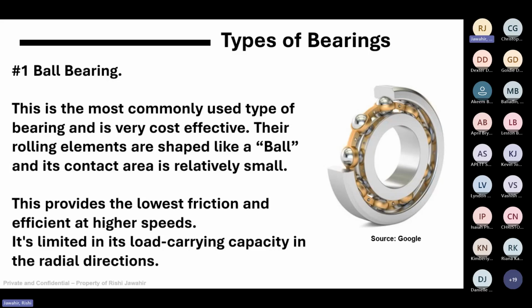So, as for example, you may have a motor, you may have a pump. That pump or that motor has what is known as a rotor, and that has a weight. And these bearings provide numerous functions. One main function is supporting the weight of those rotors, also to provide an ease of friction, so there's a smooth rotation. So these provide support in the load of these rotors.